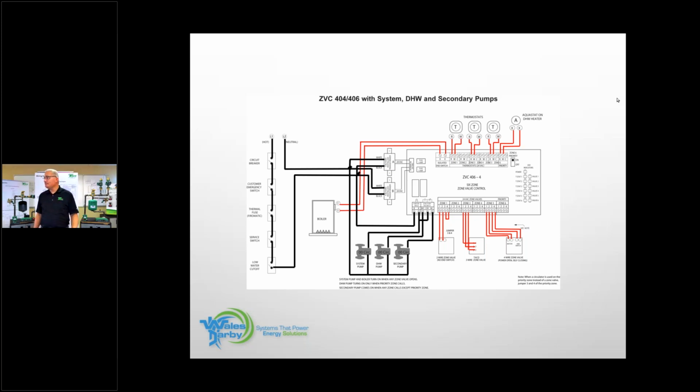We've got a question. Okay, so one of the questions is, why would you utilize the DHW circulator on there instead of using a zone valve on the circulator? Great question, and we are going to give you a problem going forward. Flow. John just showed you how much a coil can absorb, how much flow I need to get there. Depending on the GPM that you need for that indirect will determine whether you're going to use a zone valve or a circulator. And I don't want to give it all away because we do have a great troubleshooting coming up. But keep that in mind.